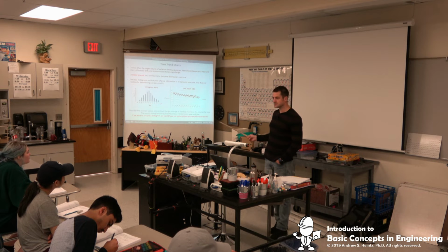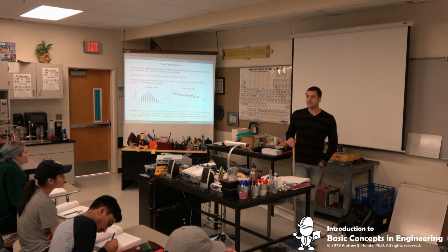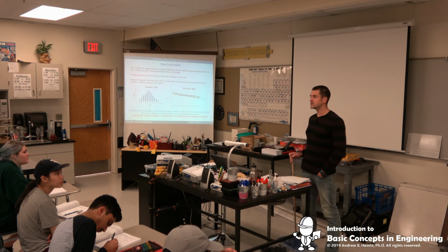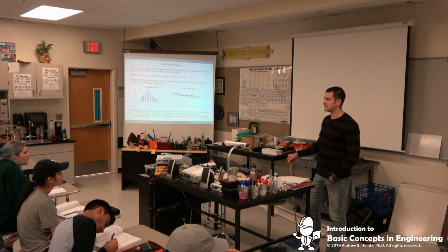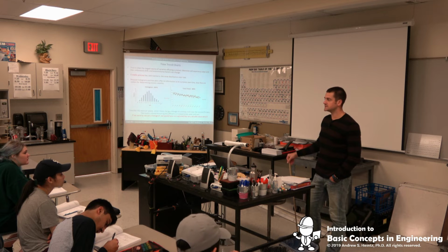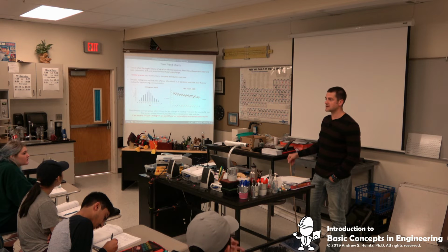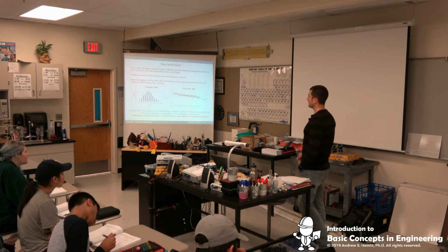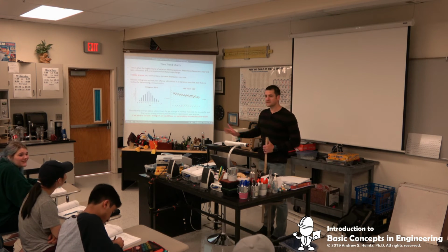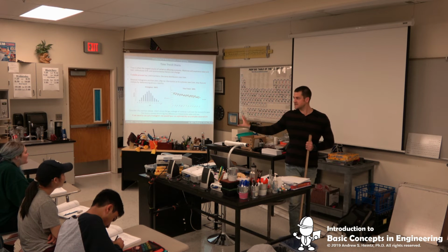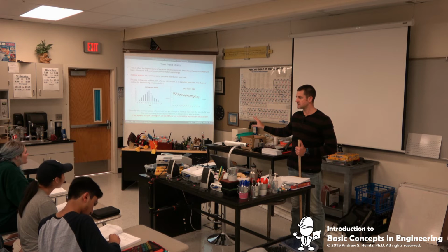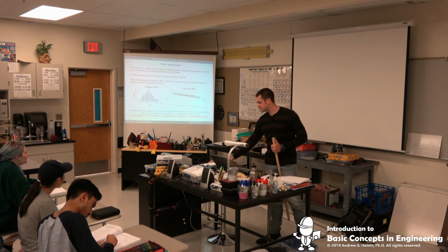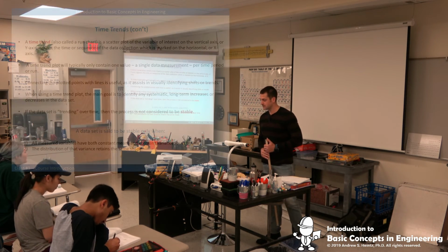Because now let's apply this to our pancake factory. If our pancake factory was trending over time, what happens when we say, okay, we got our process dialed in, let's all go on vacation? We come back from vacation, and what happens? Yeah, we're making bad pancakes. We all just lost our jobs. So in this case, if we were to use just a histogram, we actually don't gather all of the information that we need as engineers to make a decision. So we have to use time trends as well. We have to look at it over time.